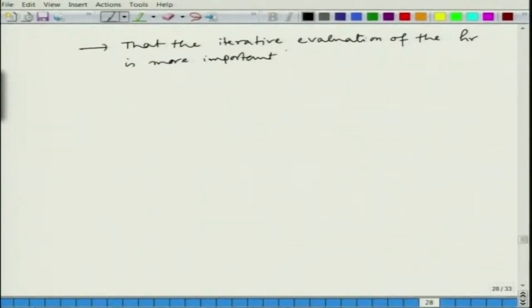So, we have seen that whenever you have a radiative term, we have to guess the temperature of the plate and then you find the radiative heat loss from there, and then you come back, find the temperature again and see how much did it change. Okay. And this iterative procedure is more important when the radiative term is dominating. So, in this case you have to do several more steps of iteration, then only you will have a converged heat transfer coefficient for radiation.